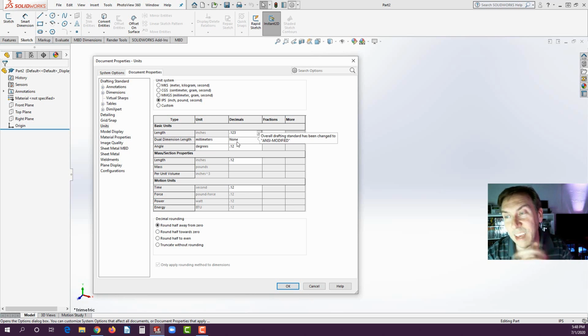So just be aware of that. When you set things at very high precision, it gets a bit more expensive. If you could design it with lower precision and still have it work and be good quality, you could save money. But 3 decimal place precision for inches is about as low as you want to go. So anyhow, 0.123. All right, and that's about it here. Hit OK.